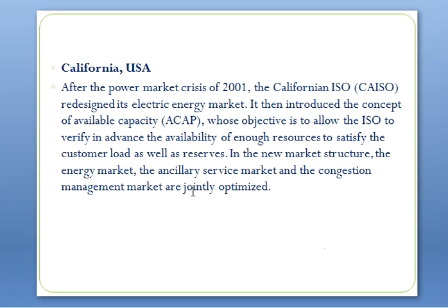For the frequency control, primary frequency regulation and secondary frequency regulation are not mandatory services. There exist up and down regulation services. The costs associated with this service correspond to capital, operation, fuel, and reduced efficiency costs. For secondary frequency regulation, the service must be available within 10 minutes and should be supported for at least 2 hours.